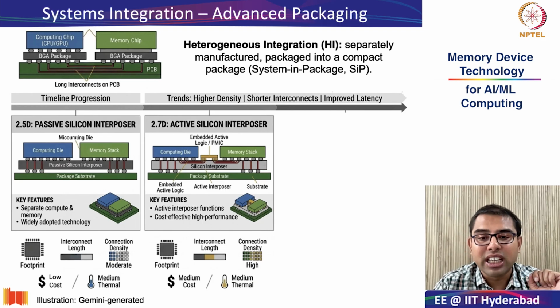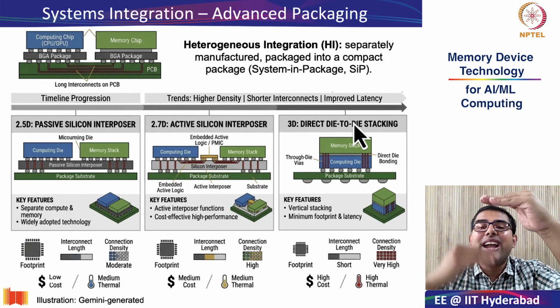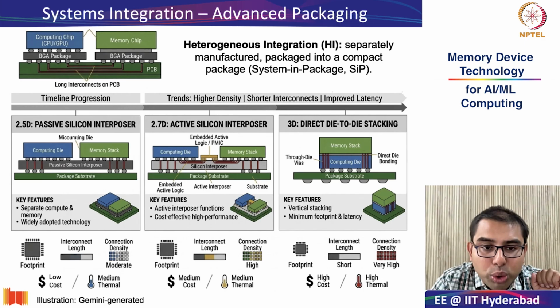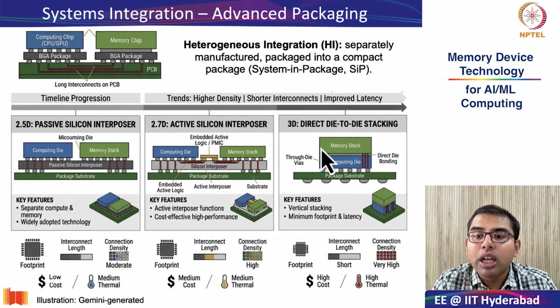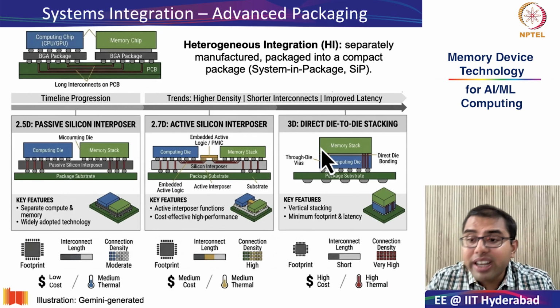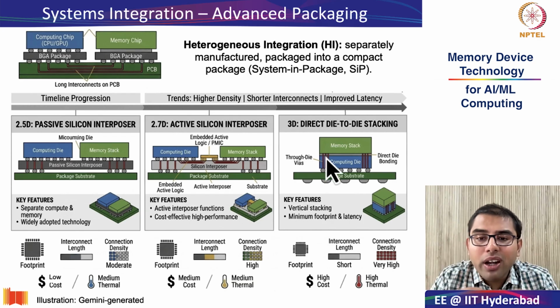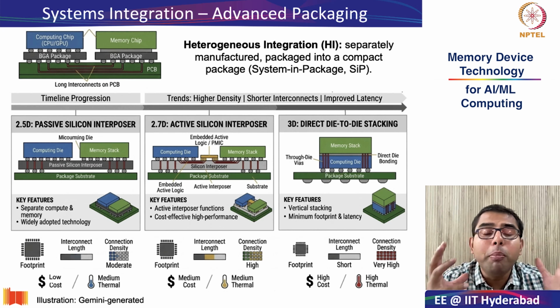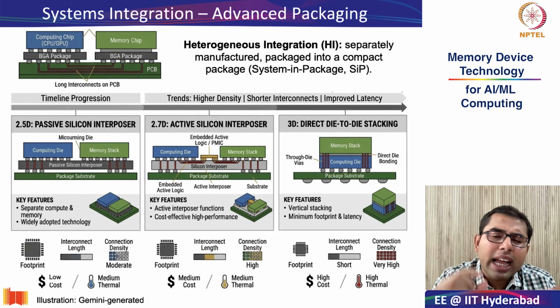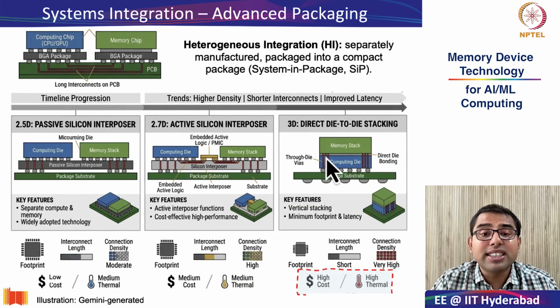However, we should recognize that the ultimate goal is to have 3D direct heterogeneous integration. As you can see from this particular slide, here the memory stack is not placed side by side, but it is vertically stacked right on top of the computing die using very thin through silicon vias. And this results in the maximum possible footprint advantage and extremely short interconnects. But we have to recognize that this too has very severe challenges.